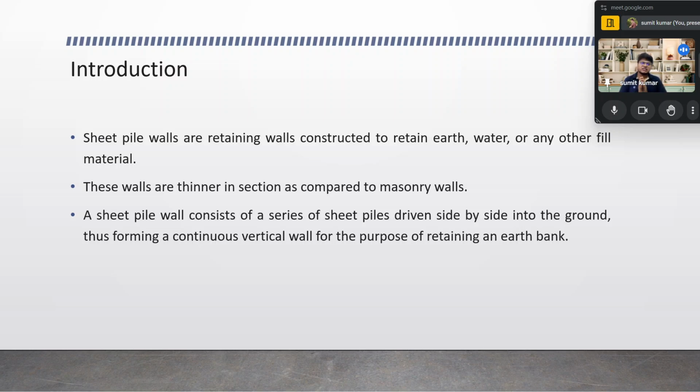If you see the construction of a bridge, where bridge foundation work is going on, first of all the sheet piles are implemented to restrict the flow of water, obviously during the dry season, not during the rainy season, because during the rainy season the flow in the river is so high that it can even break the established bridge. So during the dry season, when the river is relatively less full of water, the sheet pile walls are used to isolate and quarantine some sections from the water flowing into them, so that the foundation work of the bridges can go ahead.